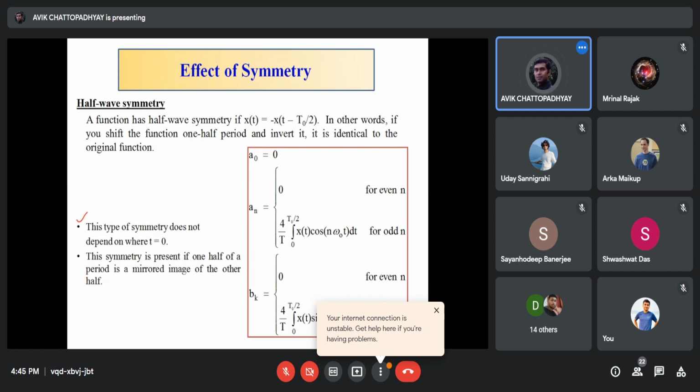But this is a very smart and judicious approach that people adopt: you first observe how the amplitudes of the different harmonics are varying with frequency, and from that you truncate, take a portion, and that is good enough. That means in practice we are dealing with a finite number of terms, not the infinite, though the series is infinite.